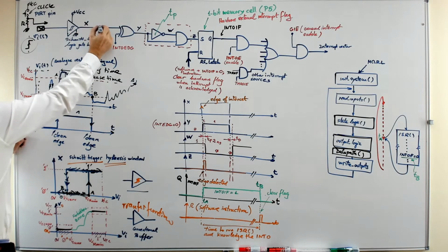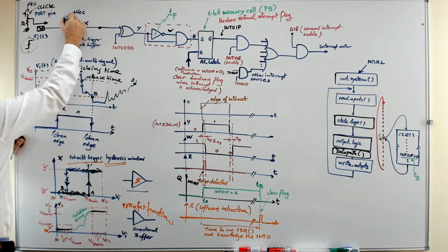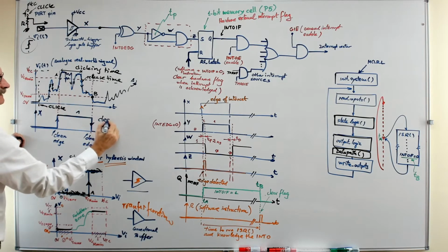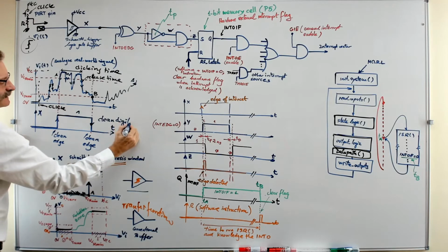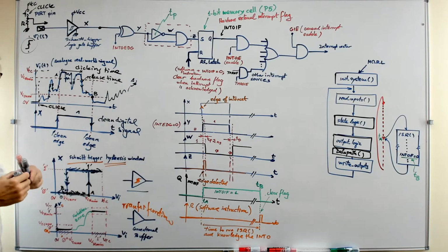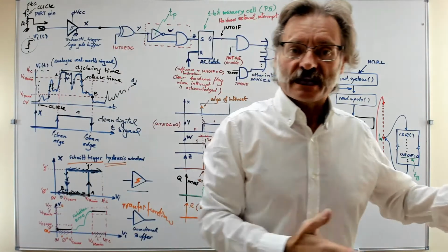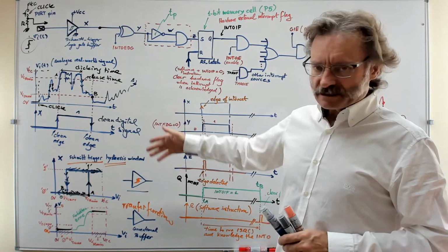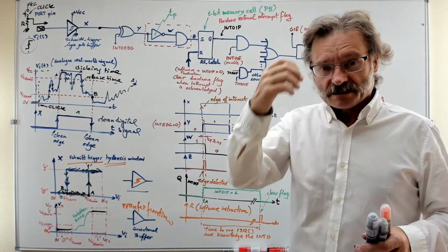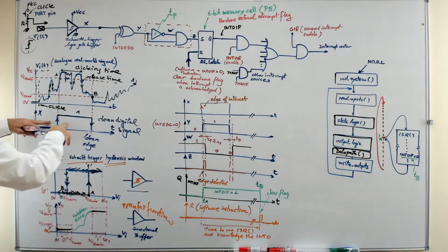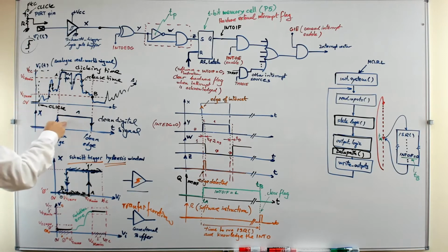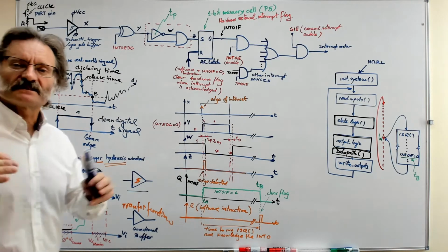So here, you may say in this wire at the output of this Schmitt-trigger buffer, what you've got is a clean digital signal, pretty much the same that you've been used to all the time for processing whatever you like in the digital world. So that's it. Then what? Well, here you have clearly two edges, the rising edge and the falling edge, because you click the button and you release the button and you are generating these two transitions.